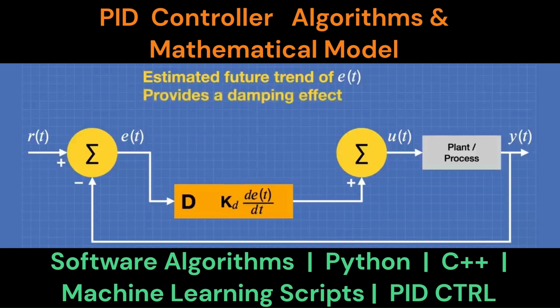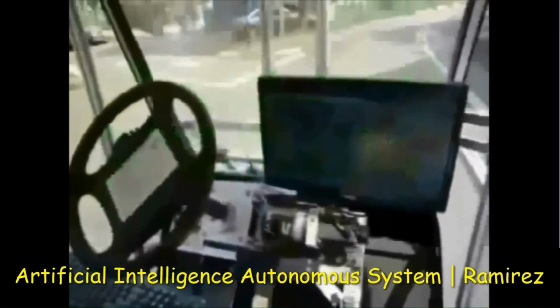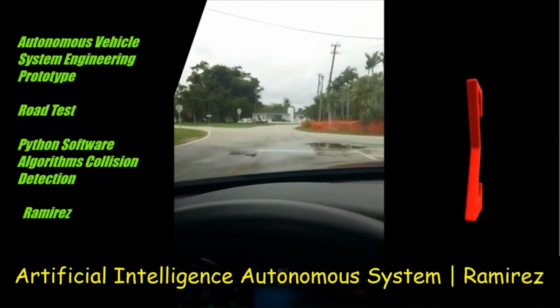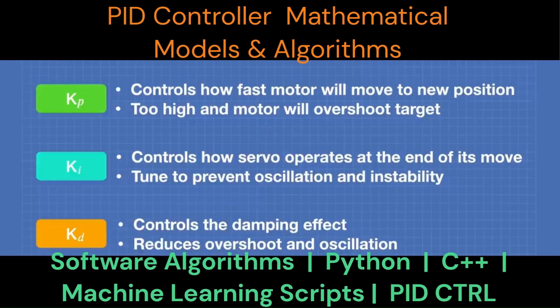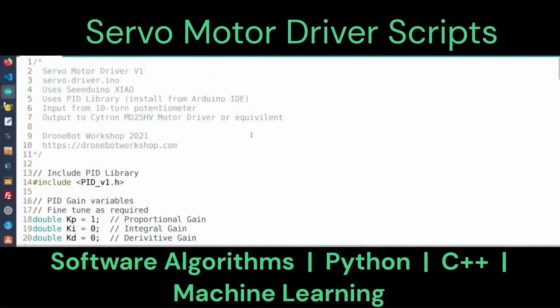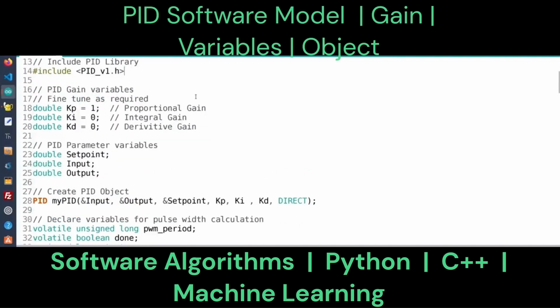Now let's set the width output pin number as it is indicated on the software module presented in this video. Set the motor drive direction pin number. Then set the analog to digital converter resolution to 12 bits and initialize the PID controller.